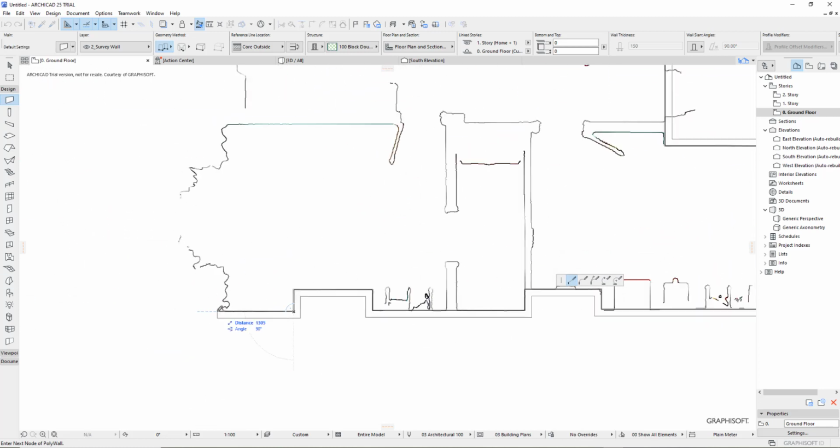Now here comes a case in point of when 90% of the success of tracing over something like this happens on site. You saw there that I've missed the left-hand flank of this fireplace. Had I put the scanner over here, I'd have picked that up. But also here, this is actually a bay window. My bad, when I captured the space, I forgot to open the curtains, so I couldn't see the walls. So for the purposes of this, I'm just going to cheat a little bit and make sure the bay window goes in.